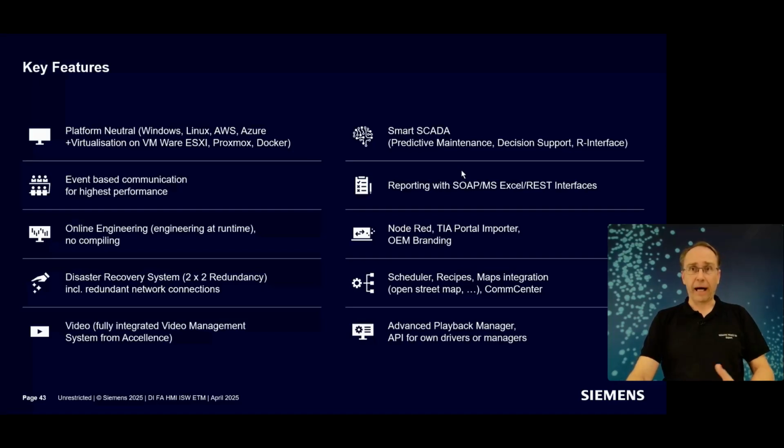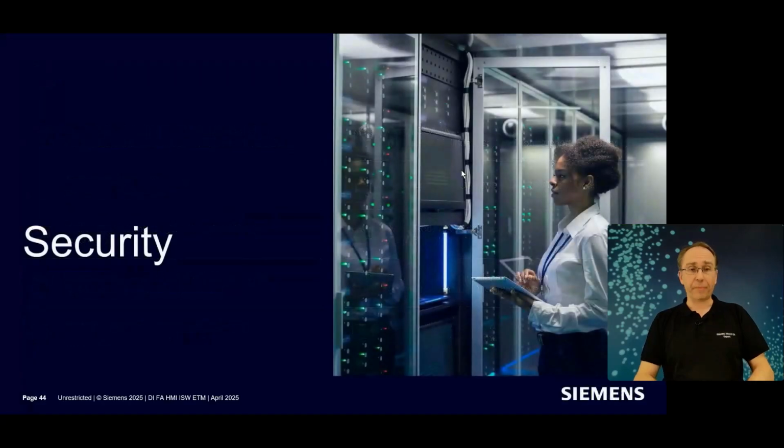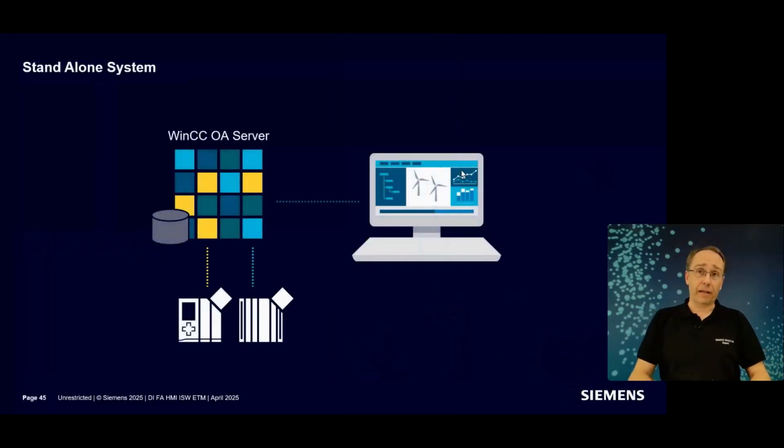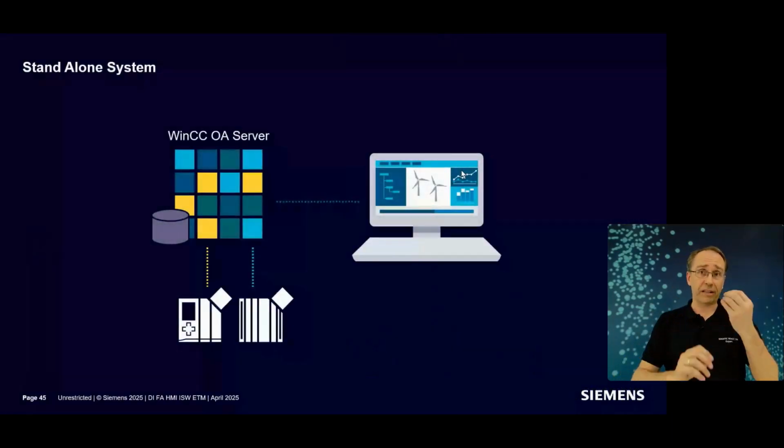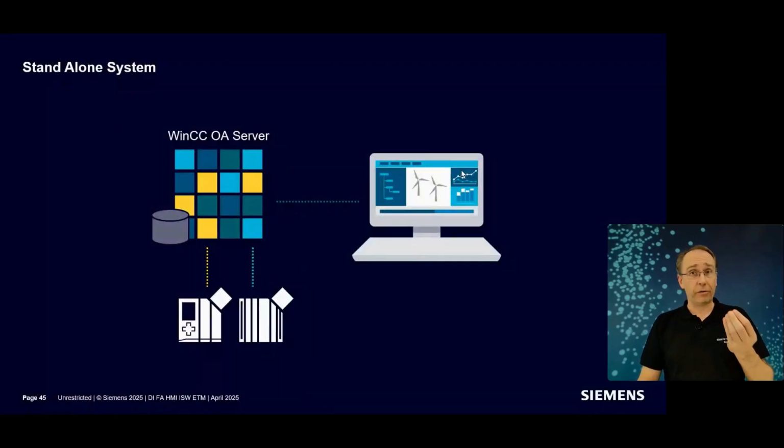And this is why actually all of the things you did see at the ProveIt was able to happen, and why WinCC OA is capable of that tremendous scalability and flexibility. Final statements here: security. All of this will be forfeit, of course, when you are hacked and when your application is brought down by some external bad boys. And this is why our system, no matter if we start with a small standalone system, all outgoing connections are, of course, encrypted. We can use different methods here.